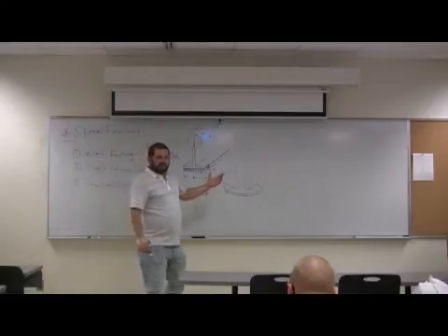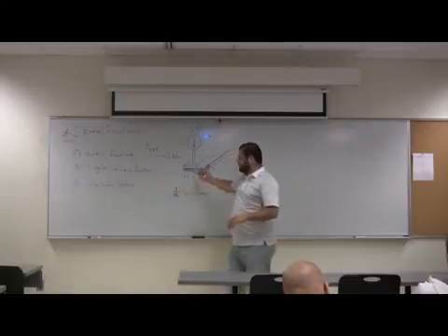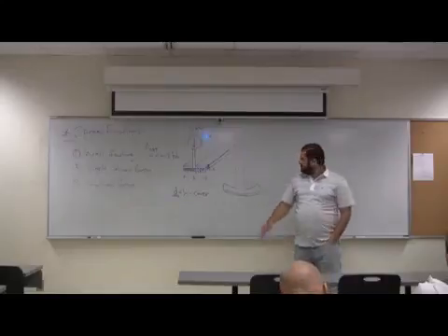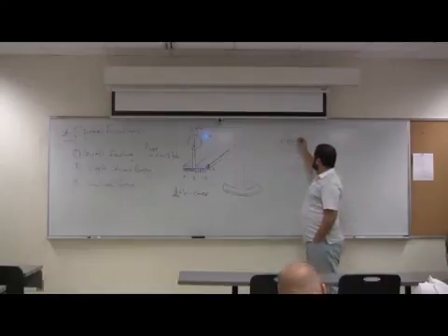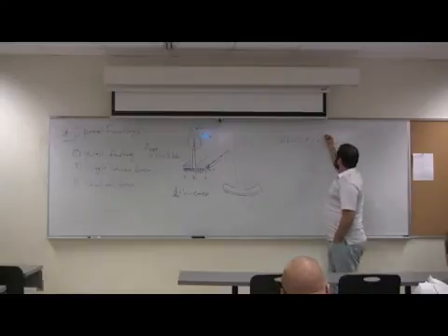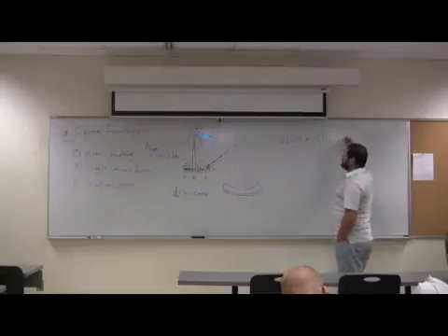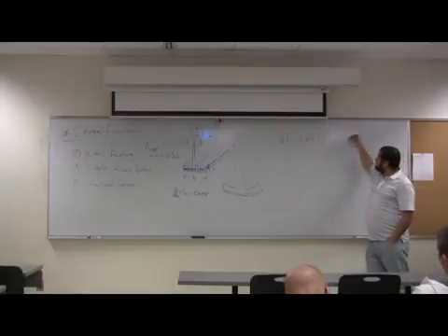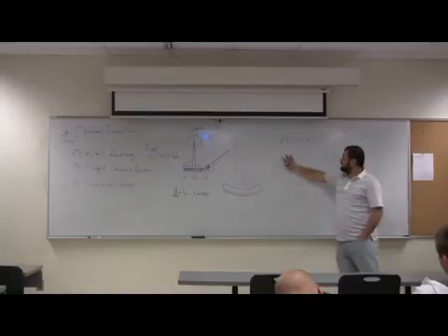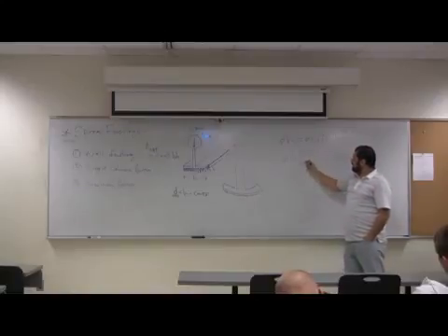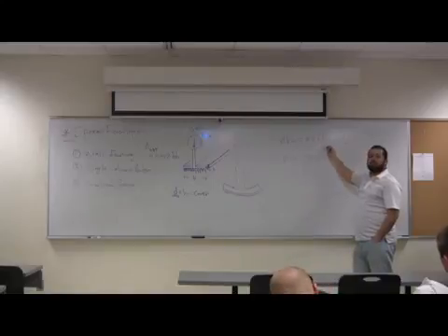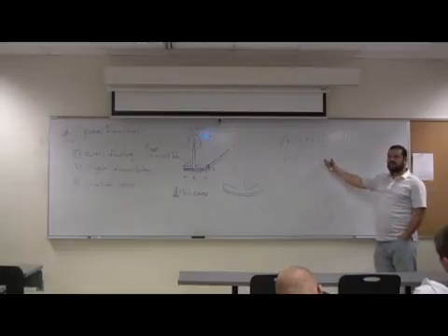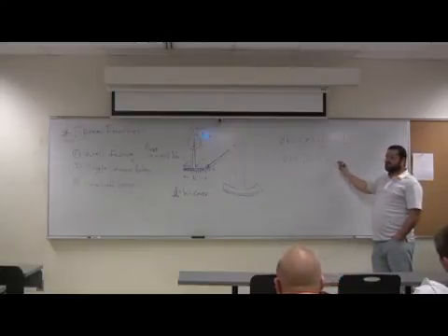So how about d? d needs to be used in the flexural calculation for the steel here, and needs to be checked for shear. Remember, phi Vc equals what? phi 2 square root of f'c b d. So we need d to check that. This must be greater than or equal to Vu at the critical section. Where do we take the critical section?